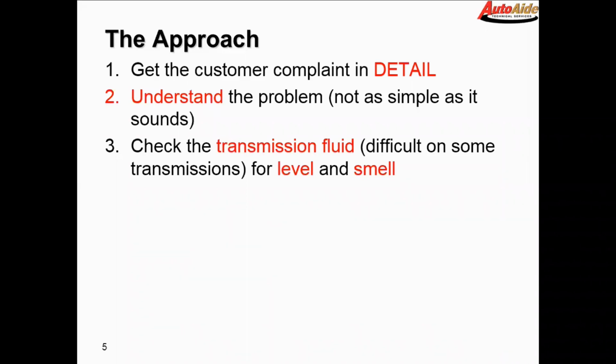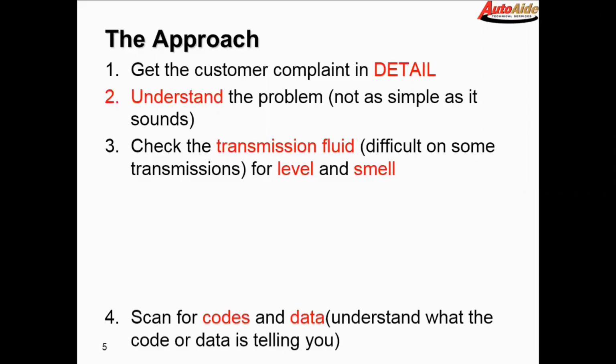And I used to be pretty adamant about smelling the fluid, but I've seen a lot of late model stuff where the fluid looks okay and smells bad. There's really nothing wrong with it. So smell's not as important as it used to be. But regardless of how hard it is to check the transmission fluid, it does need to be checked, especially if you've got range codes or gear ratio codes or that kind of stuff.